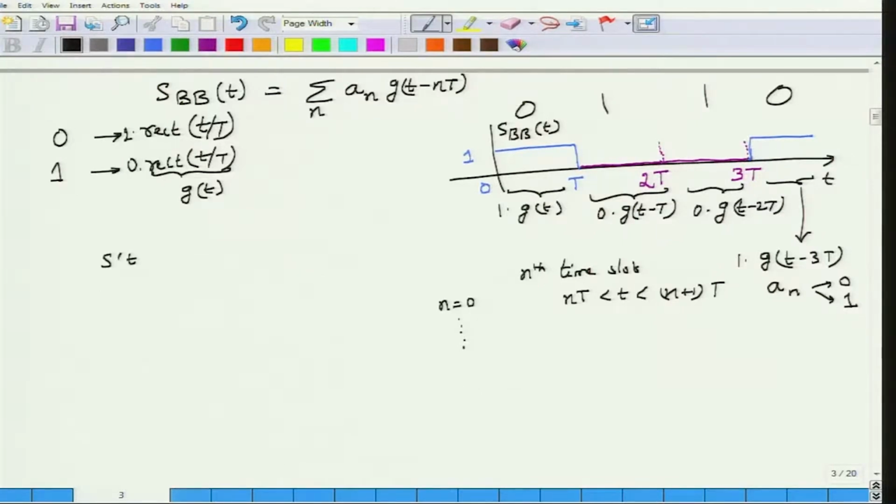For the passband signal I will not use any subscript, I will use s(t). If you go back to the earlier modules, we had shown how to represent the passband signal. So you can represent this as square root of 2 cos 2 pi f_c t, this would be the carrier, and the square root of 2 is used just for normalization purposes, to normalize the energy of the passband signal as well as its complex envelope representation, something that we covered in the previous module.